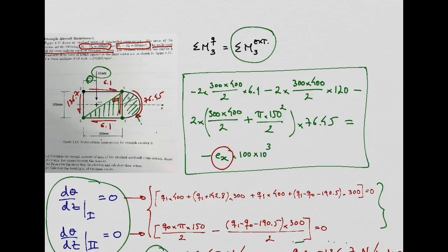So you can imagine when they come up with a new design of a wing and wing box, they need to do a lot of iterations in the actual wing. So they want to do very quick calculations, right? That's why structural idealization is important, because these are simple things you can put in MATLAB or in Excel, and get these shear flows and the location of shear centers. If the location of shear center is not good, then you can do another iteration, and Excel does these calculations automatically for you. This kind of stuff they do there, okay?